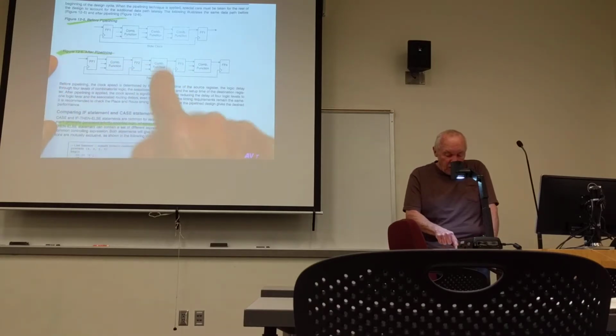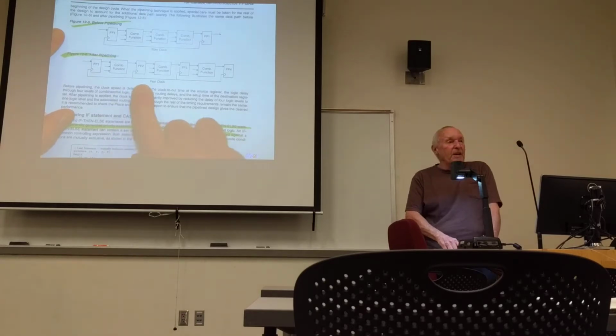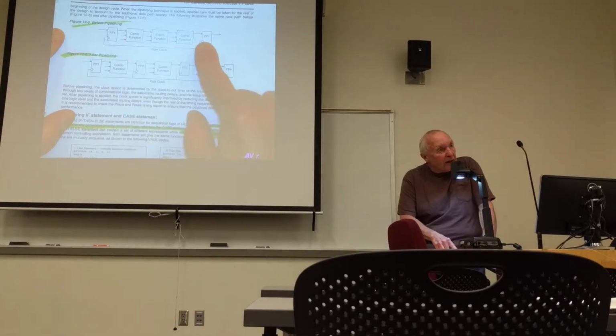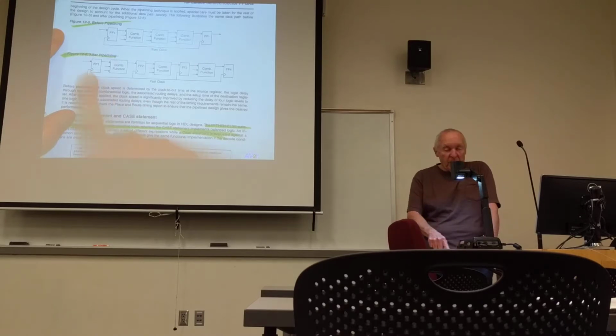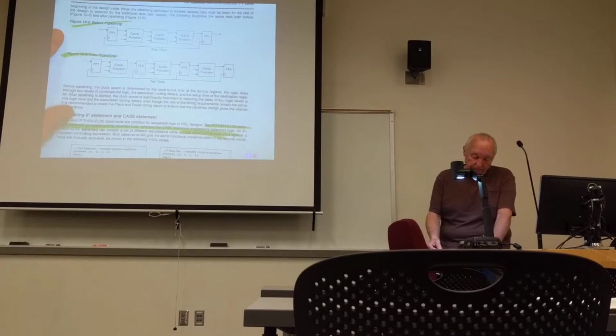So different stages in this pipeline are working on different data inputs. My clock period now only has to worry about going through the propagation delay of one block, not three, so I can have a faster clock. So this is a much faster design and may help you meet timing constraints.